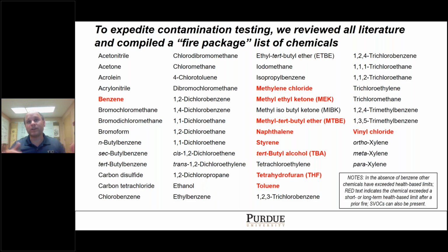They had to basically bring the system back and stabilize it with oversight of the government agencies, and they worked together to do that. Once you get that type of control back to your system, you have to go after chemical contamination. And this is where you have depressurization, localized or widespread. You have to know what chemicals to test for. And this is an issue. This is the list, right, that I'm showing you here. This is the list of chemicals that you should be testing for.